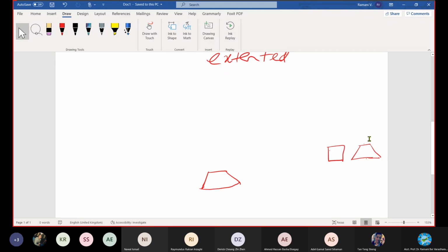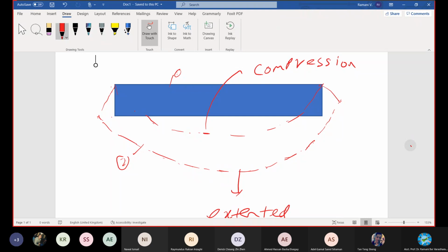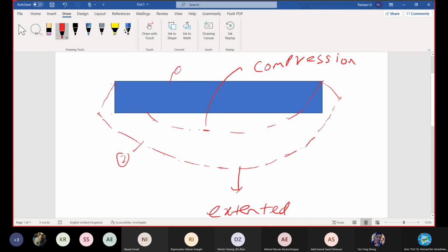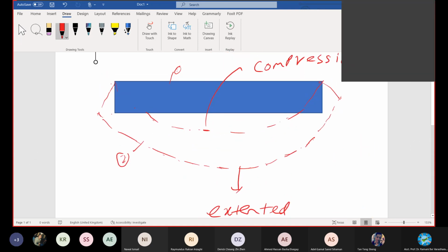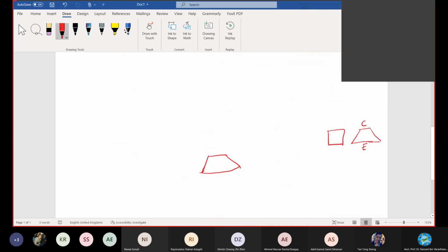The inner position is contracted at this point. Here contracted. At the bottom it was extended. Alright. The top portion was contracted. The bottom portion was extended. Right. Just relate these two because it's a curvature, right? It is not linear or just a displacement. It's curvilinear, right? Hence, by using the curvilinear formula, you are able to derive the equation for the same.